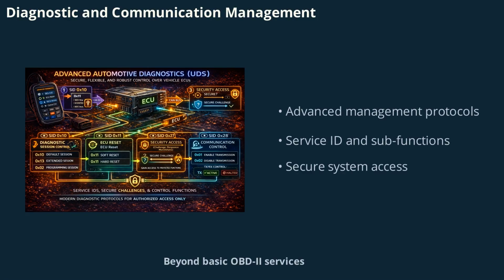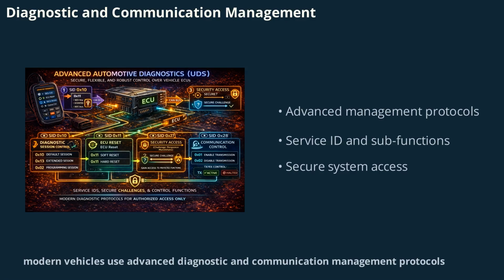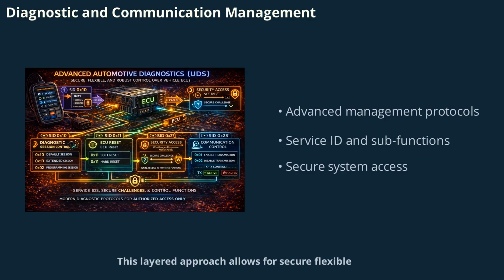Beyond basic OBD-II services, modern vehicles use advanced diagnostic and communication management protocols. These include diagnostic session control, ECU reset, security access, and communication control. Each function is identified by a service ID, or SID, and may include subfunctions for more granular control. This layered approach allows for secure, flexible, and robust management of vehicle diagnostics, ensuring that only authorized tools and users can access sensitive systems or perform critical operations.